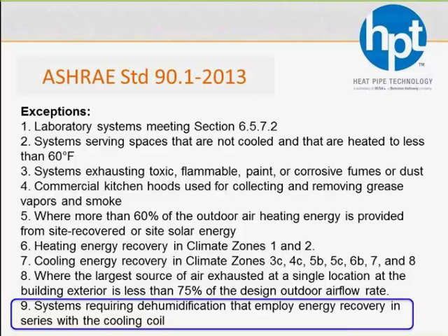So know that if you're in a tough spot, whether it's difficulty in pulling ductwork alongside the outside air, or you've simply got no space for one of the cores, or an owner that doesn't want a wheel, or an engineer that doesn't want to use a wheel, their options are not going away. The wraparound heat pipe is there and will meet code. So know that putting that wraparound heat pipe in there will meet code all by itself. No other energy recovery is required.